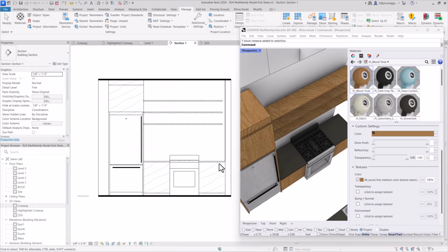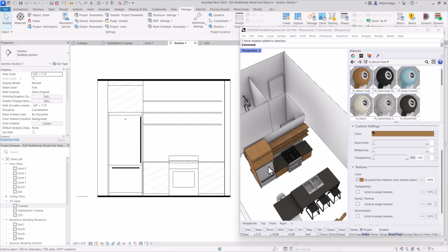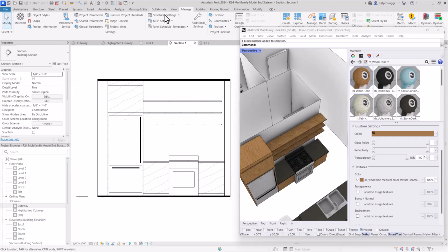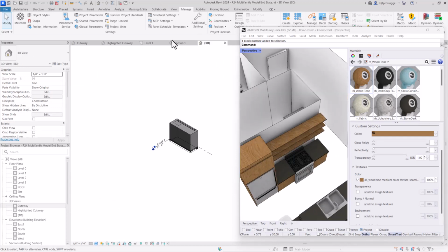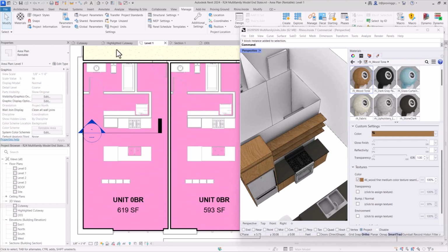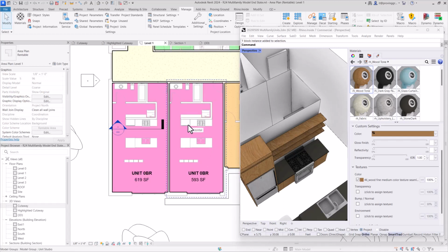So here you can see that did add a surface pattern, and anywhere that you have these materials that have been imported, it's going to have the same effect. So you don't need to go in and change it for every different version of import that you have sent in. It's always going to retain the same material name between Rhino and Revit, and you can quickly make adjustments as needed.